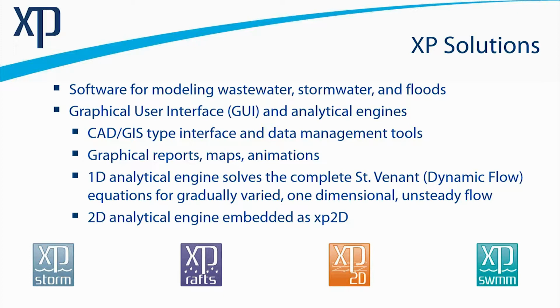We generate graphical user interfaces and supporting analytical engines to undertake our numerical calculations. Importantly, the calculations solve the complete St. Venant equations, otherwise referred to as the dynamic wave equations, for gradually varied one-dimensional and unsteady flow. And we also have a two-dimensional engine which is a module we call XP2D.